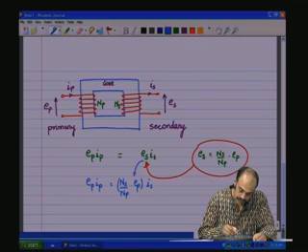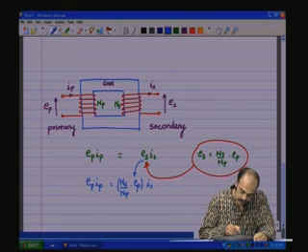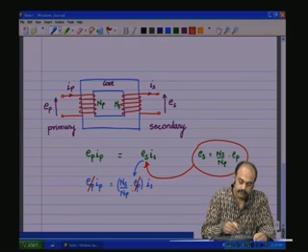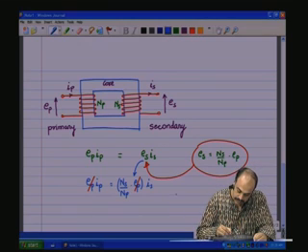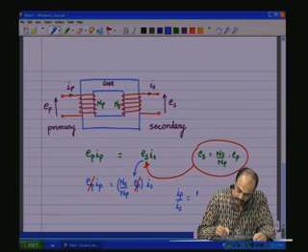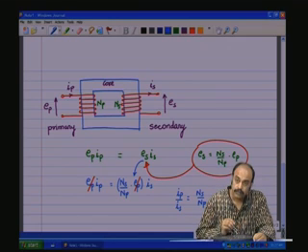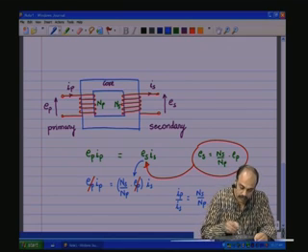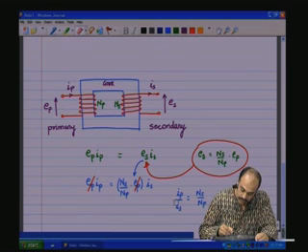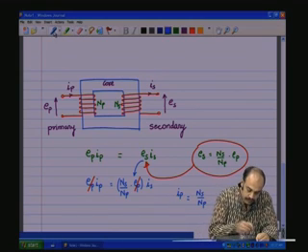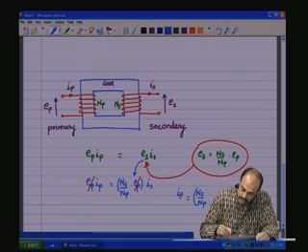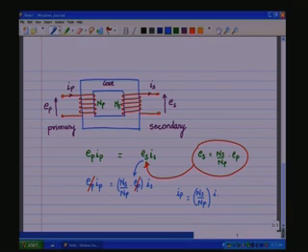So, this is Es. So, we have Ep on both the sides, we remove that, and this results in Ip by Is, which is equal to Ns by Np, or Ip is just equal to Ns by Np into Is.